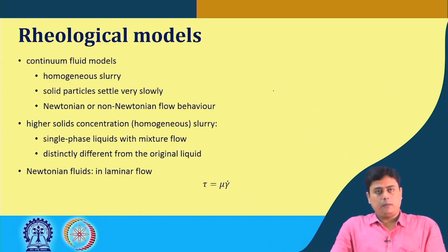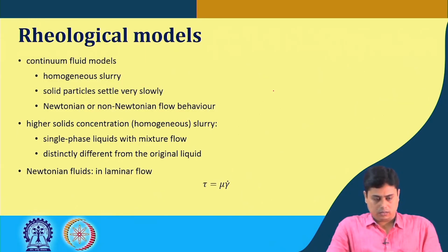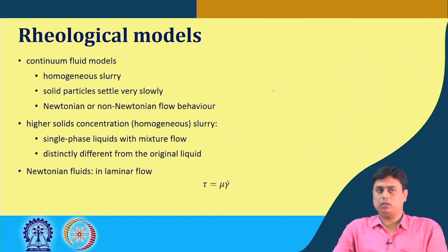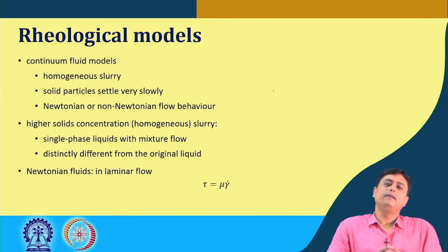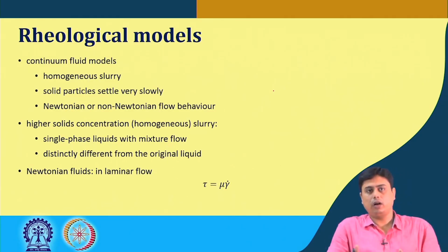Here, typically all the models for the rheology of slurry transport are based on the continuum fluid models, and that is valid when the solid particles settle very slowly, or remain suspended till they reach their destination, or for a longer time.